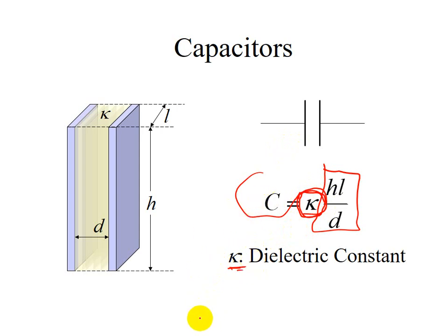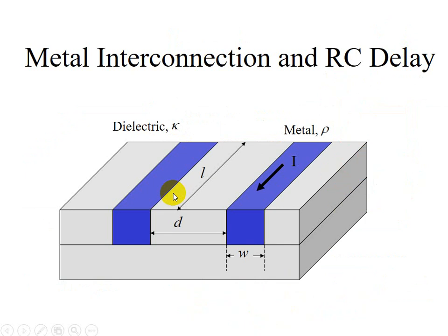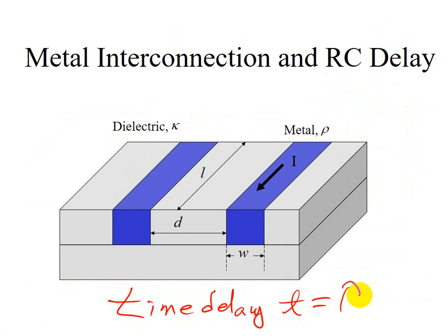So not only are you developing high K dielectric material for charge storage devices, you also need to develop low K dielectric material to reduce the time delay, equal to the resistance of the conducting wire times the capacitance of the insulator.